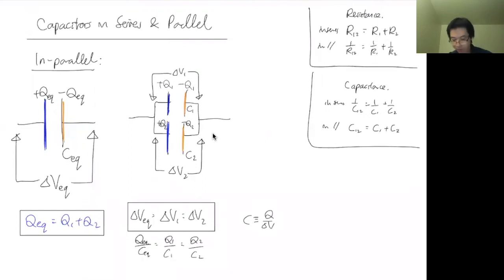All right, so good. What this will help you with is, let's say if you know C1 and C2, and if you know Q2, you can find Q1, right? So for problem solving, don't try to memorize every single one of these relationships. Just know these three facts: the definition, plus knowing how to derive this out of your labeling, and then you can deduce all these things in your homework problems. We'll give you, for example, C1, C2, and tell you what Q1 is, and then ask you what Q2 is, and this is how you can find it.